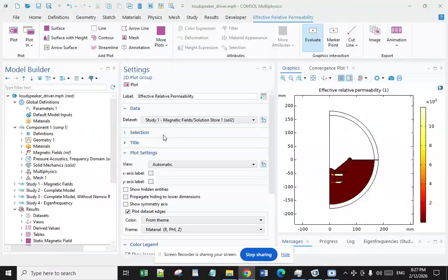Electromagnetic acoustic transducers are suitable to generate all kinds of waves in metallic and/or magnetostrictive materials, depending on the design and orientation of coils and magnets. Shear horizontal bulk wave mode, normal beam or angle beam, surface wave, plate waves such as SH and Lamb wave, and all sorts of other bulk and guided wave modes can be excited.